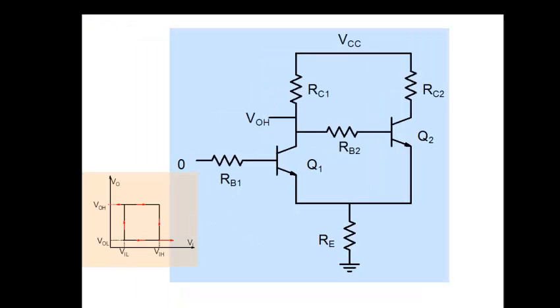All right, so keep this picture in mind here. This is how my circuit should work here. Okay, so when the input is low, it should remain high, and then switch at VIH. Then when you come back, it should not go up at VIH. It should remain low, and then come up at VIL. So that's what we are looking for. So what I'm interested in is finding out what are the expressions for V0H, V0L, VIL, and VIH, okay, from this circuit.